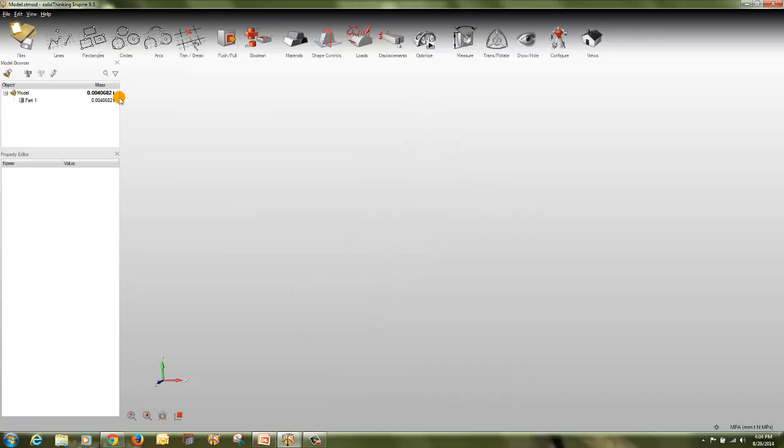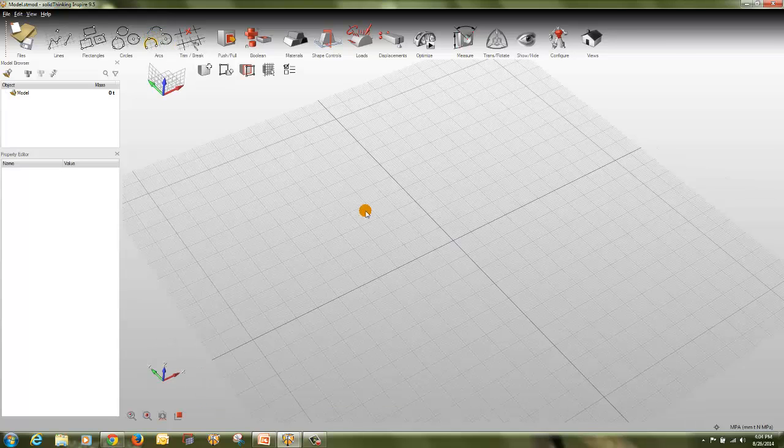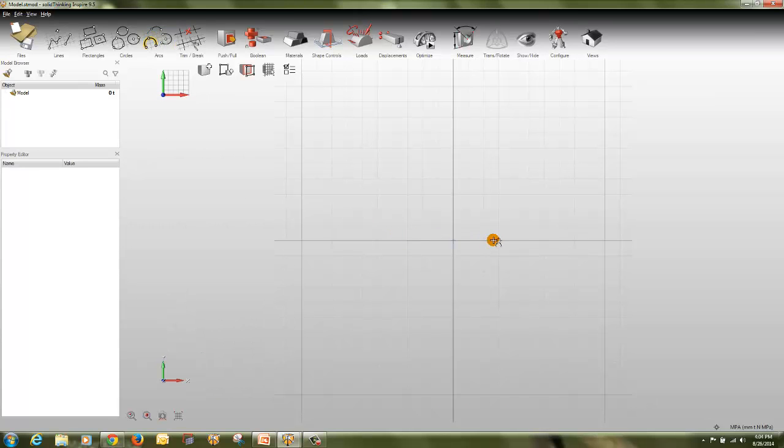So now let's move to the next tool, which is the arc tool. In the arc tool we have three options: arc by 3 points, arc by center and ends, and arc by the tangent to end. So we'll start with arc by 3 points. So the first point, second point, and the third point. This will create an arc. You can change the radius, say 20. You can change the degree also.